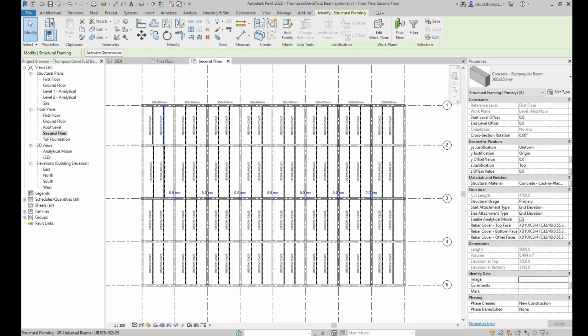all the, first of all, we're going to change all the beams. So bar the beam systems, the structures, your girders or your primary beams as they're called, we're going to change all of those to 300 by 500 mil deep. And then we are going to change all the perimeter beams. They're going to become 300 by 350. And then all the beams along grid line 3 are going to become 300 by 350.